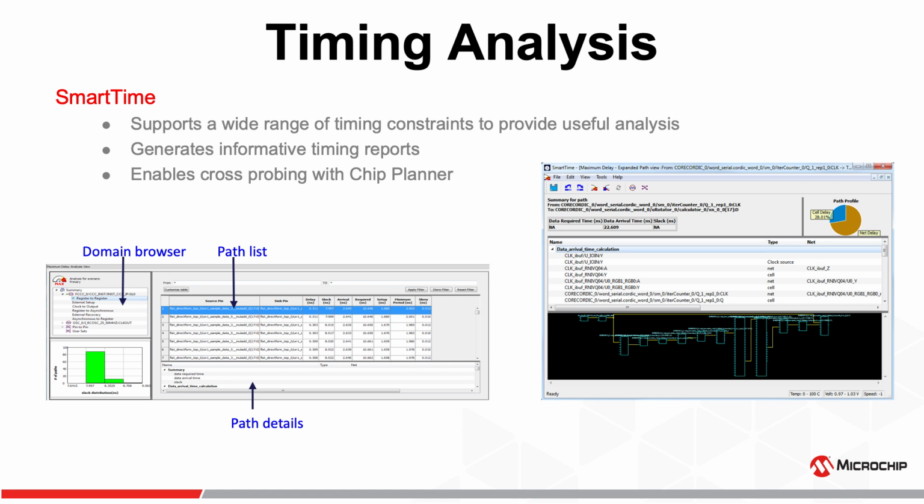If the slack is positive, then the timings were met, and for each path, each source pin and sink pin, it will show you the delay and the slack value, arrival time, required time, setup value, and it will also show you the skew value.